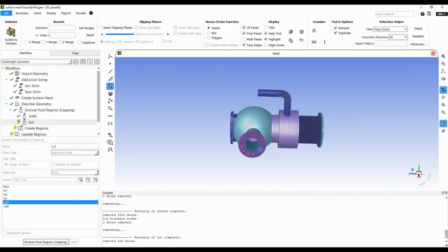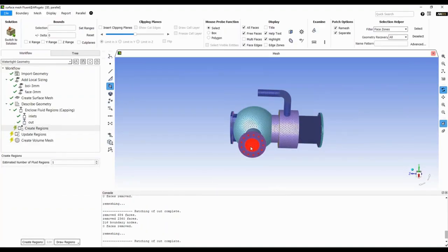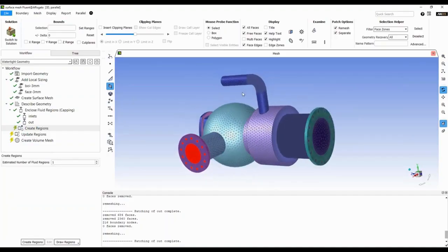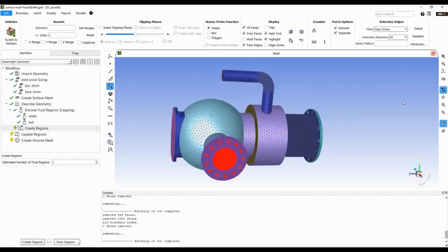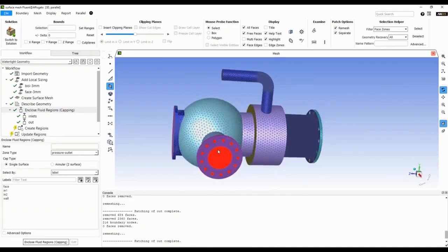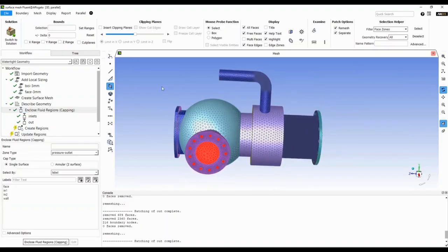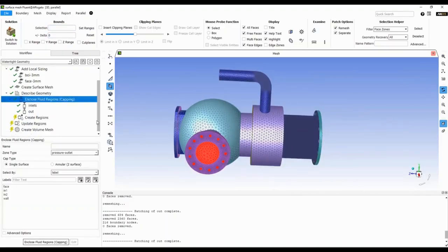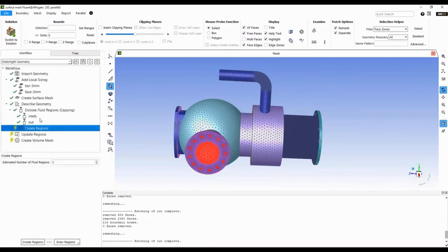And one very nice feature, the reason I immediately knew that was a mistake is because it was green. In Fluent meshing, the inlets are, well, they're not here right now. The inlets are green and the outlets are labeled as red. You can change the colorings in the options if you'd like, but it's a nice way so that I can immediately catch mistakes like that.